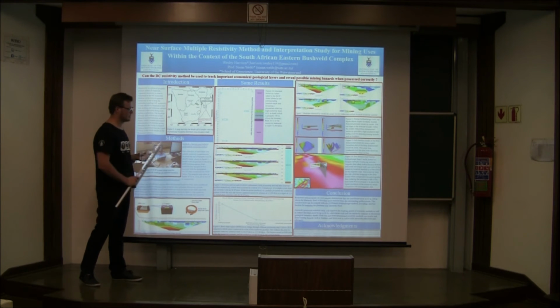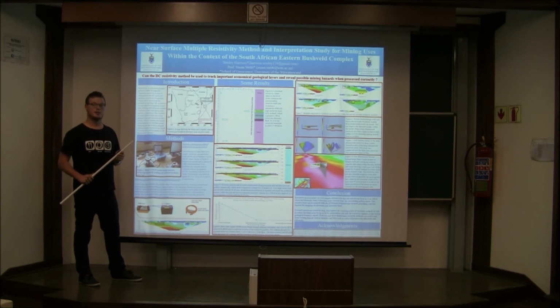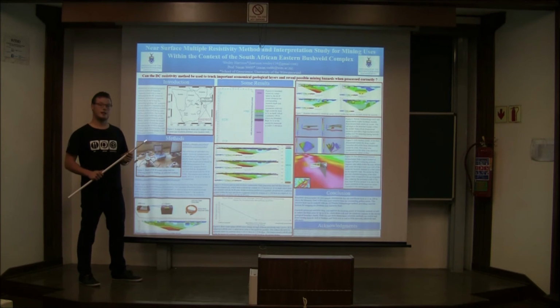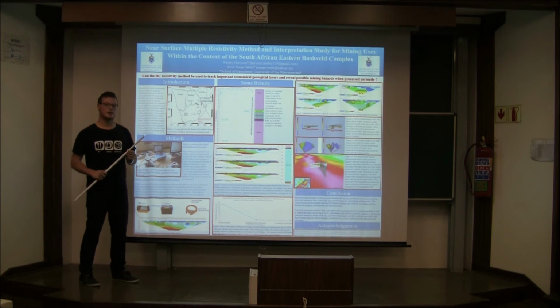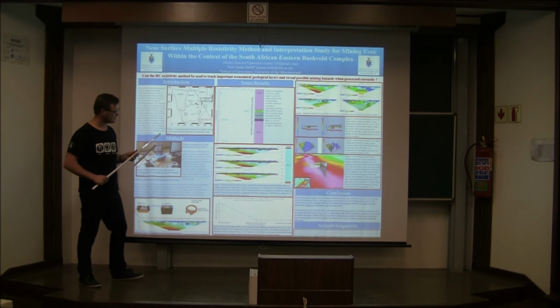We also found that for some profiles we can reduce the root mean square error by up to around 20%. This means that the resistivity contours themselves will be moved to the correct depths and in turn correct the geological model produced by the resistivity profiles. This shows again the importance of correctly processing resistivity data.